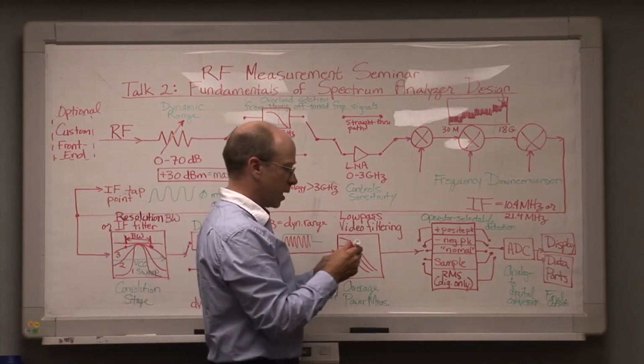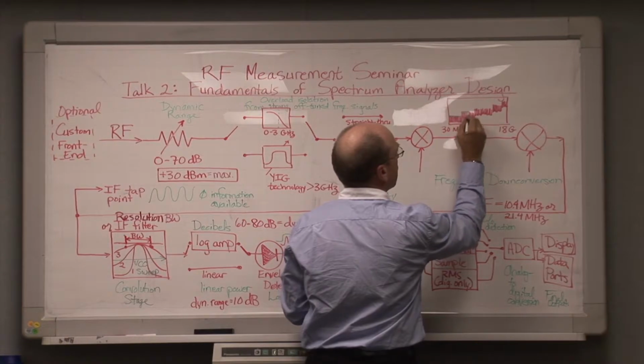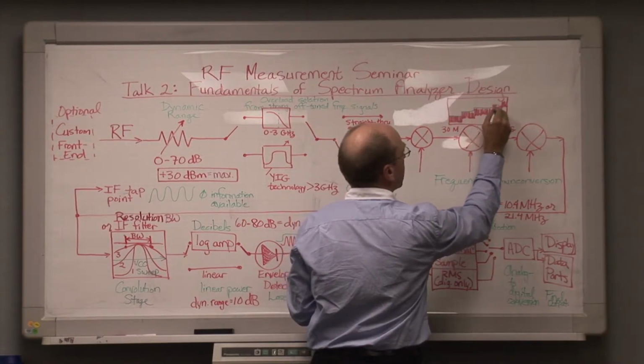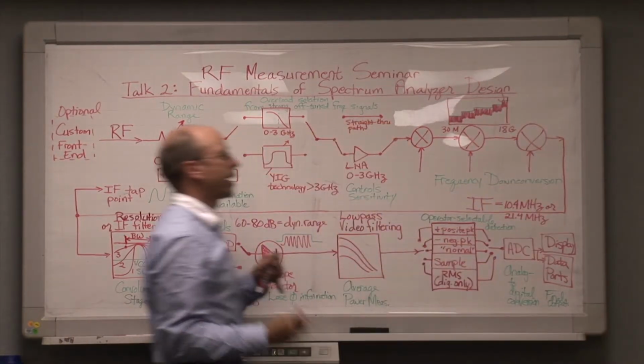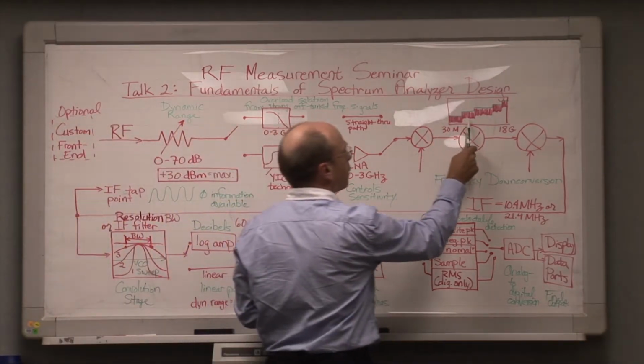What you're seeing in the stair-step pattern is the increasing noise level of the spectrum analyzer internally as a function of frequency.